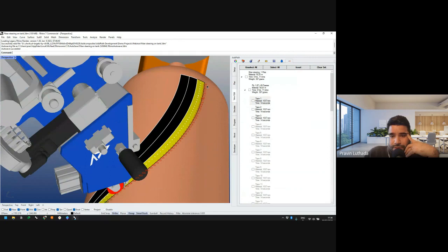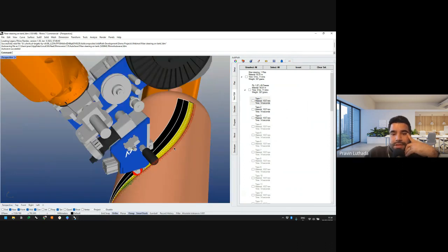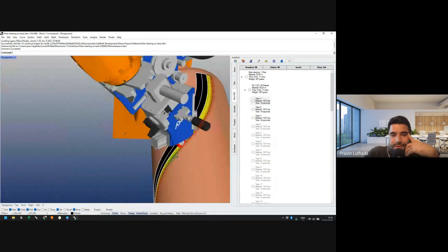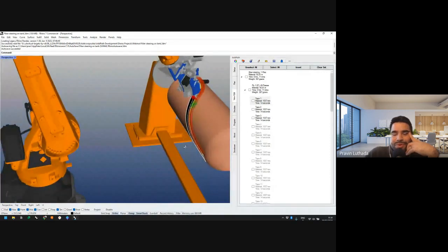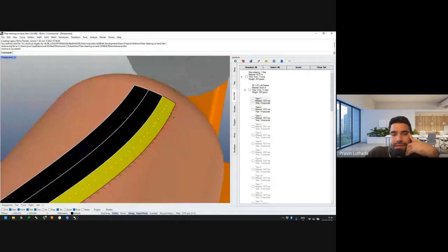So what you're seeing here is 600 millimeter steering radiuses value, which are steeper. So what you would expect here, this red indicates, is the fiber would peel off from the surface. So it may not stick. Whereas in the center section, it's okay. So even though the stress vector tells you to go along this direction, maybe this fiber width with this steering limitation may not be the best choice.